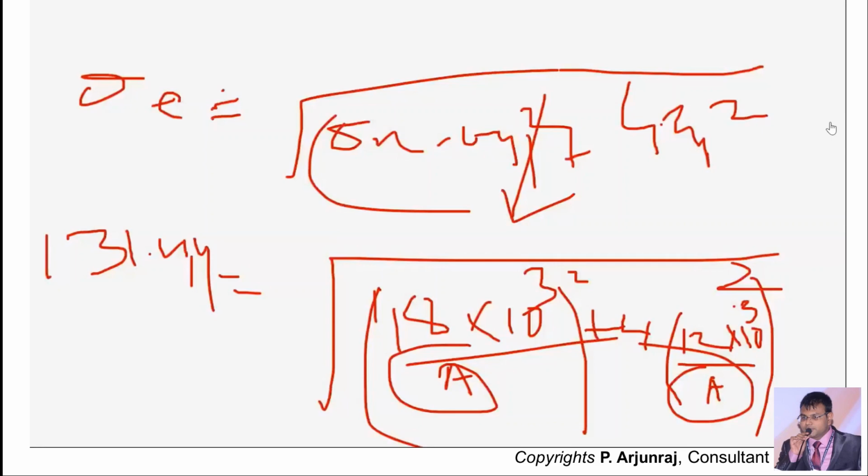For your exams also, I prefer you to use the scientific calculator, so you can reduce the calculation time. It will take 5 minutes, and parallelly I will solve the problem using the scientific calculator. Maybe we can also get the values for the diameter of the bolt. What is the area we're going to get, and after that we can use pi by 4 d square to find out the core diameter of the bolt using the maximum shear stress theory.